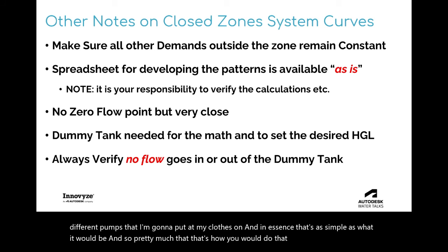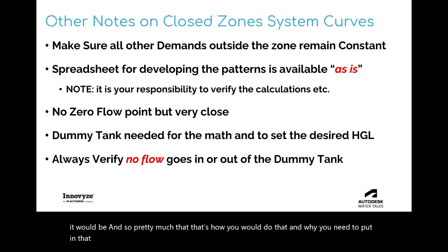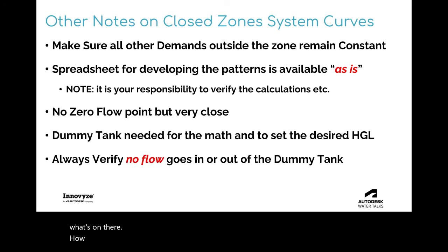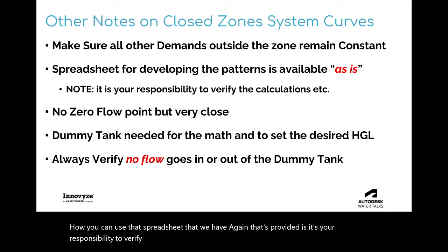And why you need to put in that dummy tank, because that's what's going to determine that hydraulic grade line. Otherwise, there's no hydraulic grade line for it to even know how to calculate it. But that's what's on there. How you can use that spreadsheet that we have, again, that's provided as is. It's your responsibility to verify the calculations that are on there, but that can help you calculate those patterns.